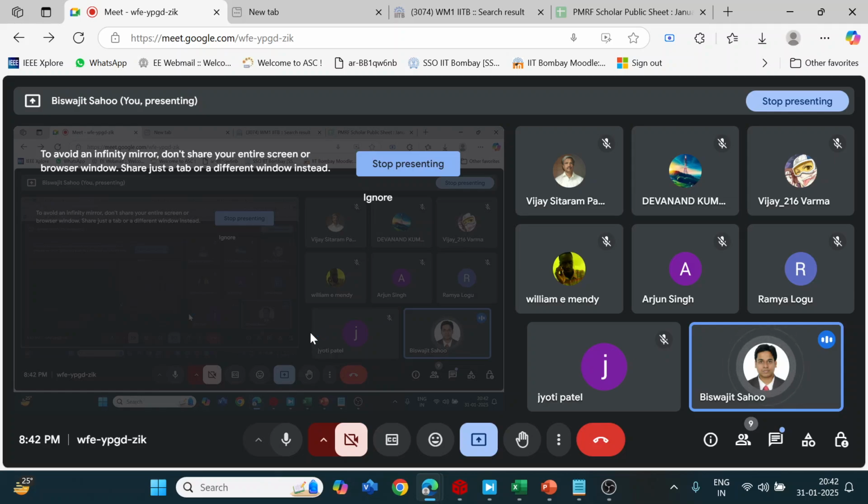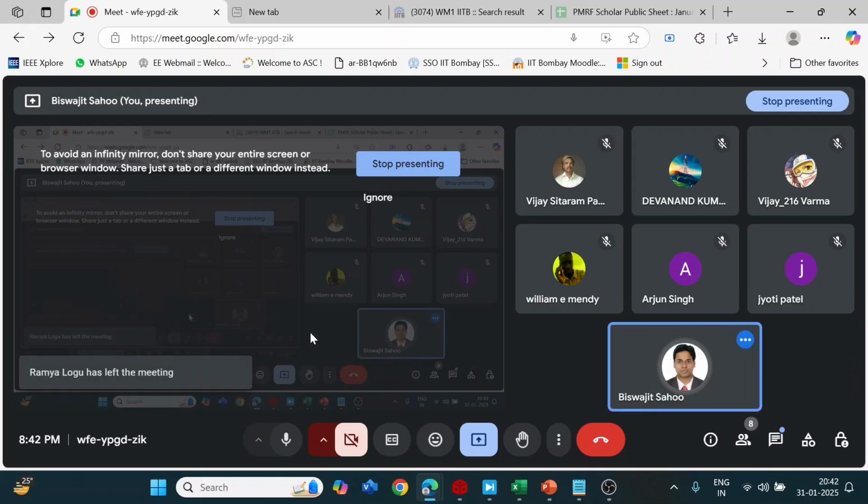If an open loop system is given to you and the question says strictly that it is a unity feedback system, then write the open loop transfer function and whatever is in the numerator, simply add it in the denominator. That gives you the closed loop transfer function. You can try by yourself. Suppose g of s, h of s equals 1, then g of s divided by 1 plus g of s is the closed loop transfer function. You will get the same answer.